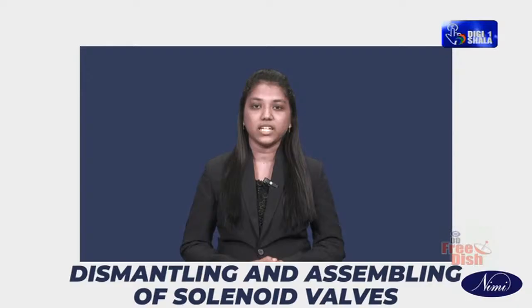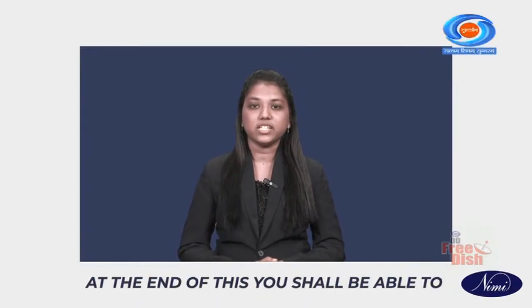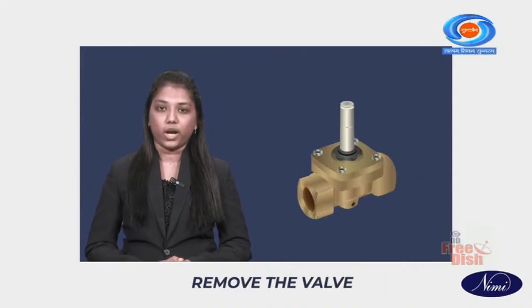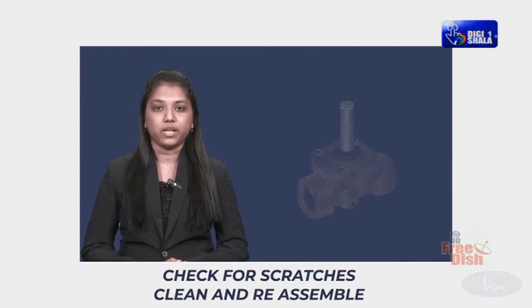Hi everyone. In today's video, let us discuss how to dismantle and assemble a solenoid valve. At the end of this, you shall be able to remove the nut, remove the coil, remove the core or metal plate, remove the valve, check for scratches, clean and reassemble.